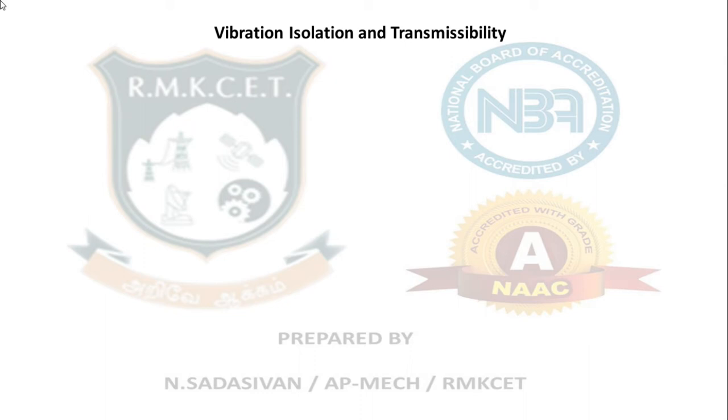What will happen if your machine vibrates? Your tool post will vibrate, your tool will vibrate. Now that is going to be replicated on the surface of your workpiece. So if your machine is not exactly balanced, it is directly going to affect the surface roughness of your job. Your job will be rejected. Your client will not pay for your job.